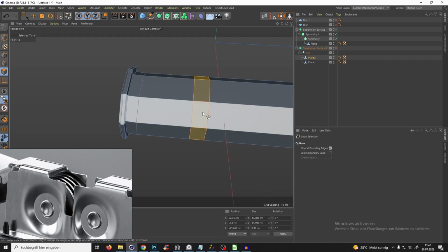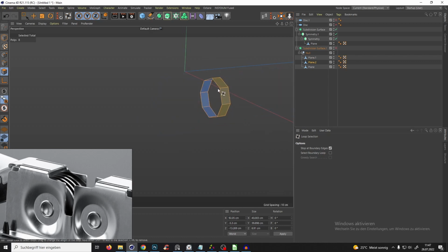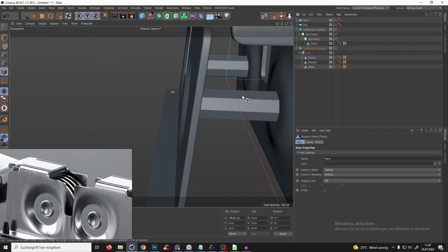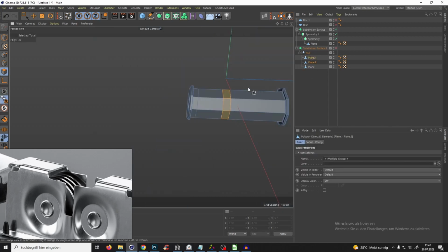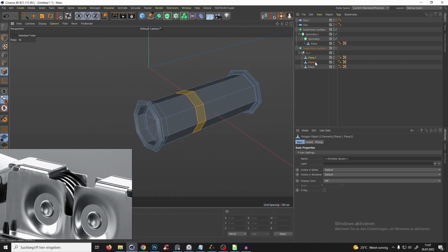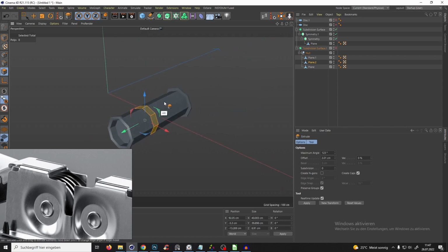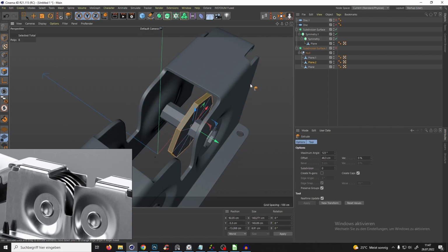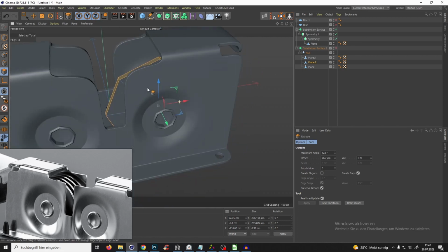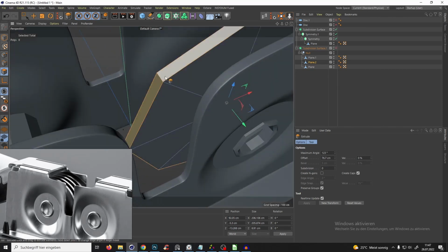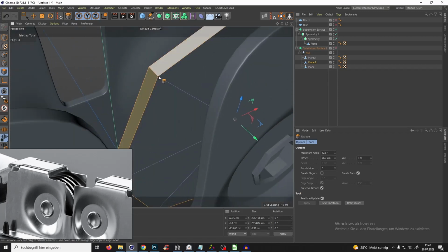And we can go again to polygon mode, UL for selecting those polygons, and again just UP, and then we have again an extra plane, and if you press Alt Q, it's just those polygons, Alt W to select those two, and just Alt Q, so we just see them, and you go to those polygons, and D for extrude with creating caps. Maybe you press Alt W, so you know how big they have to be. But maybe something like that. That's okay for now. And again, you see the edges are not straight, so we have those outer edges.